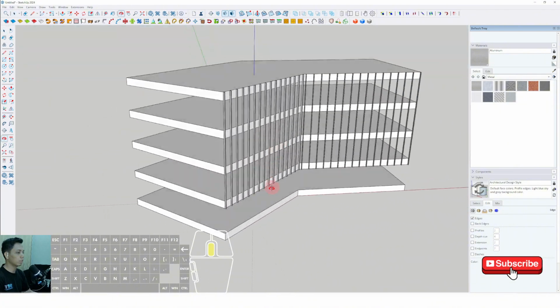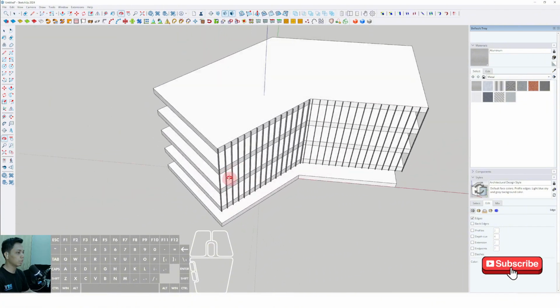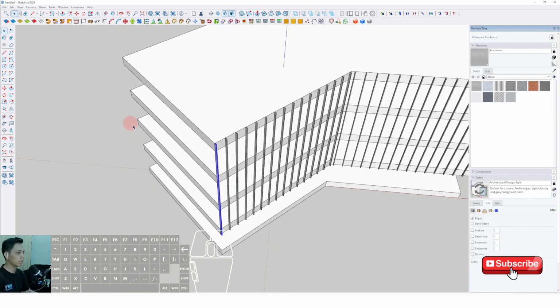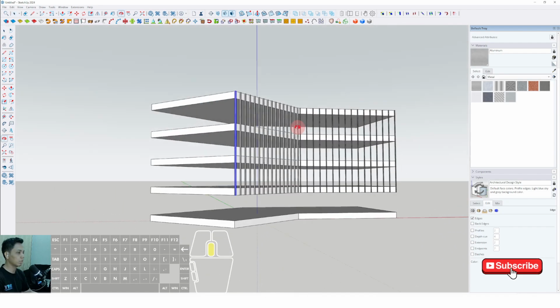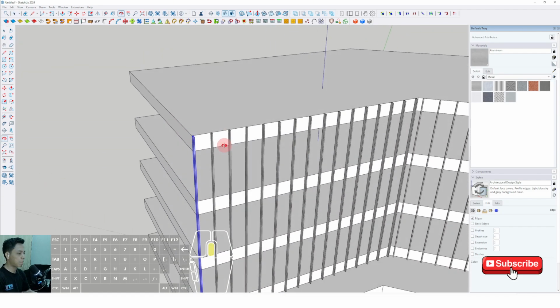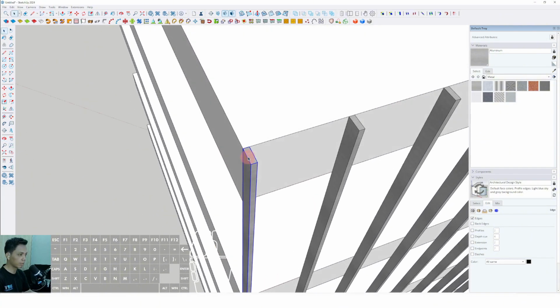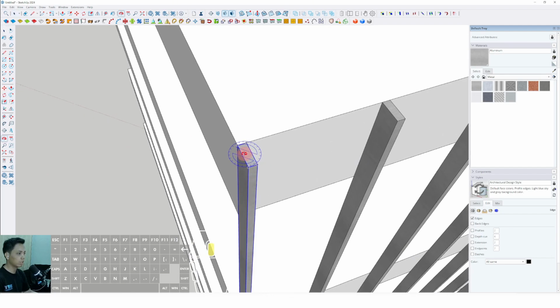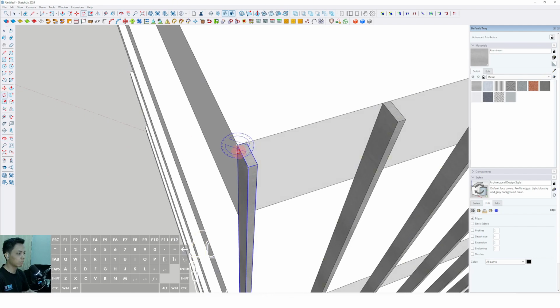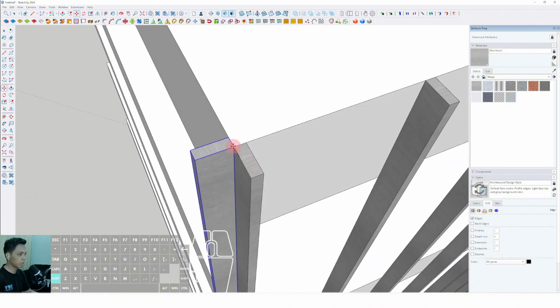Now we can make the another side of this building. We can make this another side of the exterior frame of this commercial building. Then we can select rotate. We can click this rotate, click from this point, press Ctrl. Okay, then we can type 90 degree, enter. Then we can select move and place to this position.